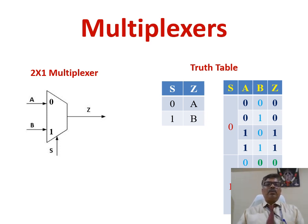If S equal to 0, that is your selection line is 0, the input which is connected to 0 input is the output. If S equal to 1, then whatever the input connected to 1 input is the output. So when S equal to 0, output is A. If S equal to 1, because B is connected to 1 input, Z becomes B.